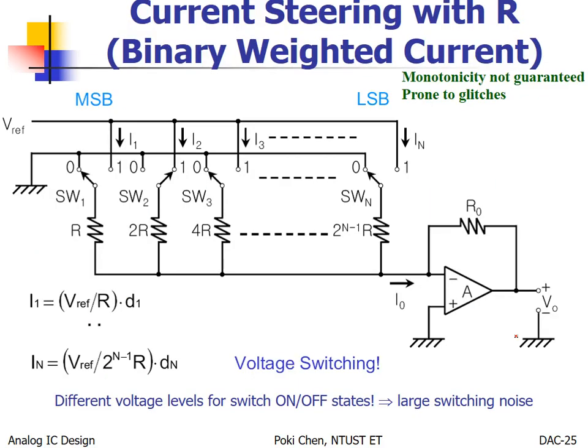All right, that is the simplest structure for you to refer because you learn it from microelectronics already. Yeah, you can see again from MSB to LSB. Why? Because MSB with the smallest resistance. It means this is AC grounded, not DC.